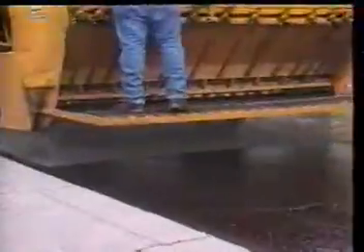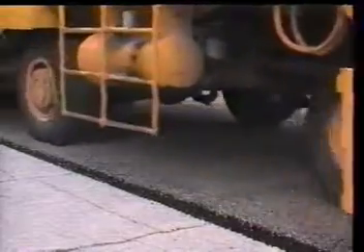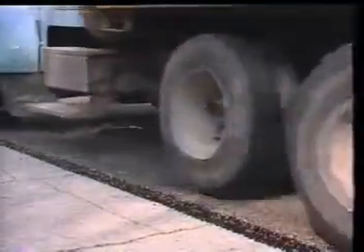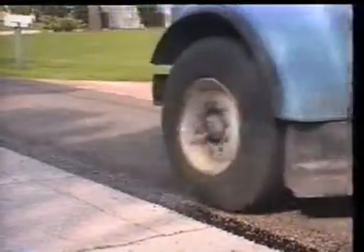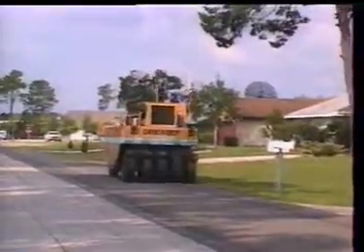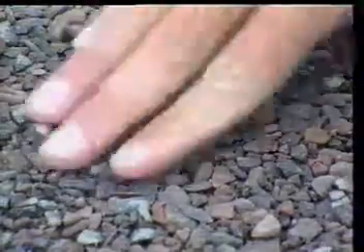Regardless of the type of oil being used, the speed of the operation is important. If it moves too fast, the chips will roll when they hit the surface. The problem then is that the chip's exposed side is sticky, so they'll be picked up by the rollers and by traffic. So look over the application. There shouldn't be any oil on the top of the chips.